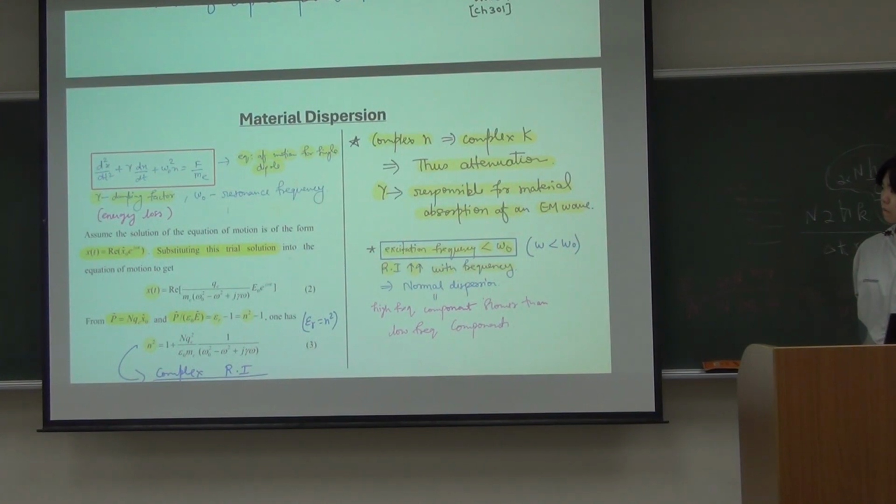So at a different frequency, you have u equal to omega over beta. Conventionally we plot omega versus beta. But beta is a function of frequency. And then we do this slope calculation and get the group velocity right at this point, at this frequency.